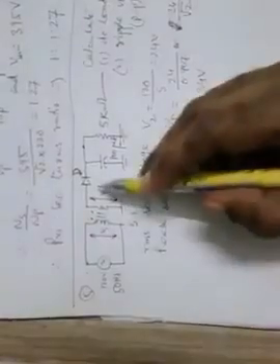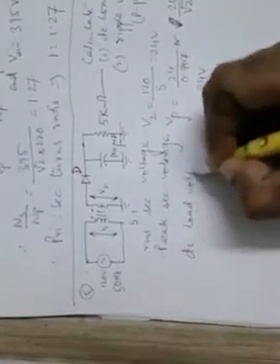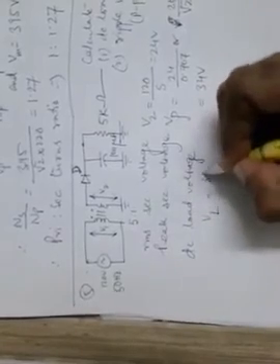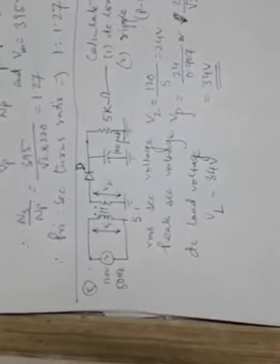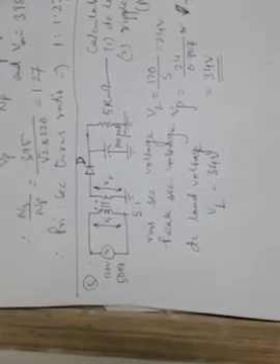Now if we consider this diode as ideal and the ripple is small, the DC load voltage VL will be 34 volt. This is the DC load voltage, if the diode is ideal, that means no further drop inside the diode in terms of its barrier potential. Now to calculate the ripple, we first need to get the DC load current.